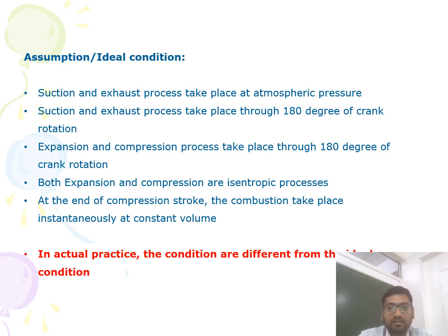Second assumption: the suction and exhaust processes take place through 180 degrees of crank rotation, meaning half a revolution. Further, the expansion and compression processes also take place through 180 degrees of crank rotation, so all four strokes, suction, compression, power and exhaust, are carried out through 180 degrees each, half a revolution of the crank.